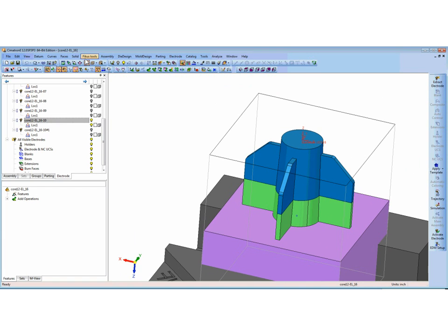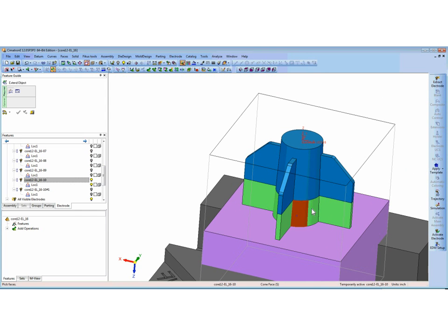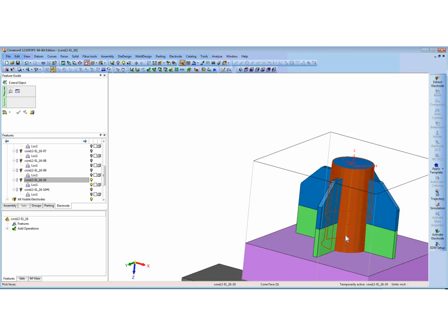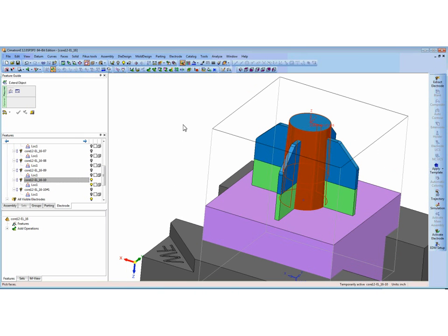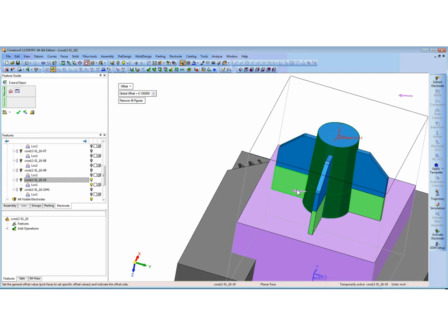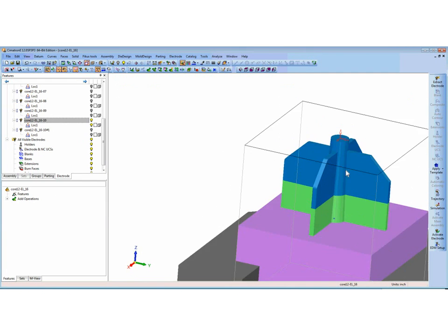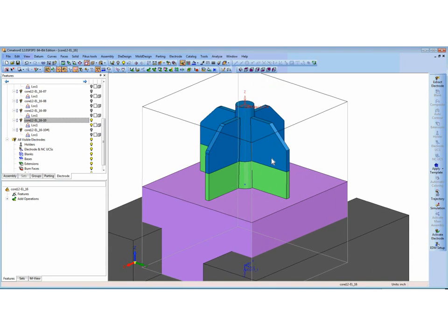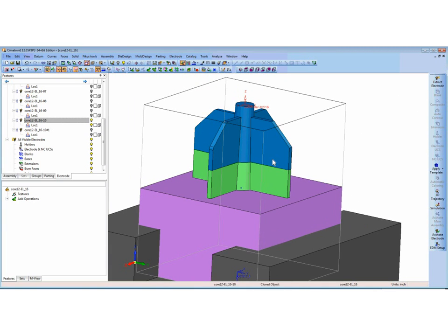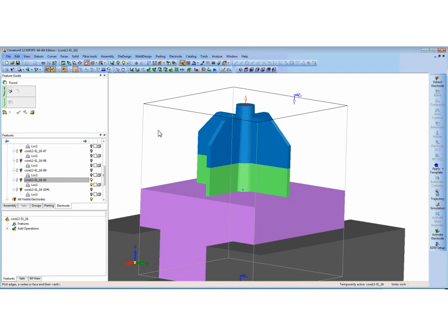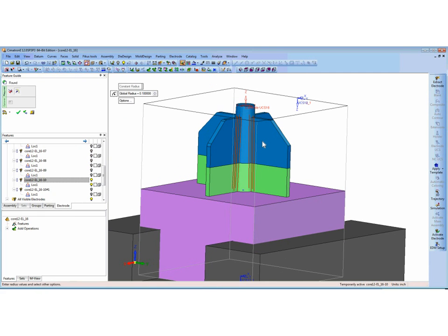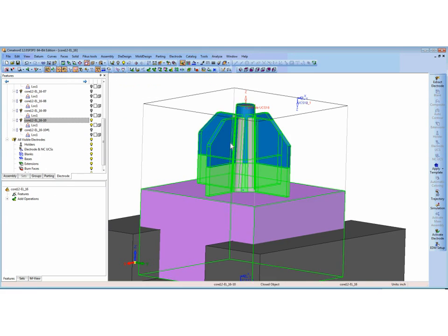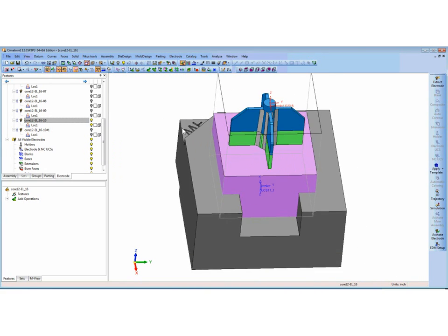We also could do a solid, extend, and just reduce the diameter, keeping it a little more rigid. And if someone else is going to be programming this, we might want to steer them in the right direction as to what size cutters need to go in there, right? So we could do a round, and again, just kind of box pick in here, get all these, and we'll make it 65 so that they know what kind of cutter has to go in there to clean that out.